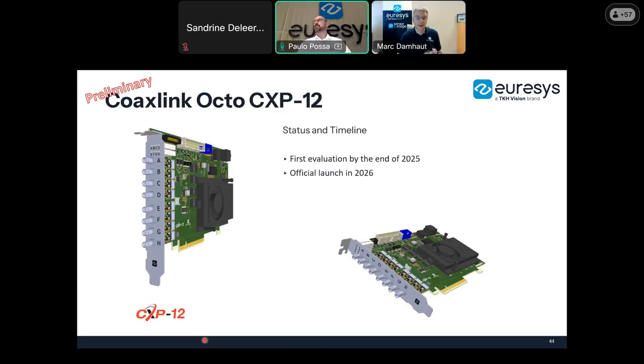The advantage of doing the pixel binning inside the frame grabber is that you move all the heating caused by this extra processing from the camera to the frame grabber. The frame grabber itself doesn't have any problem with heating because we have a heat sink that can draw all the heat from the FPGA.